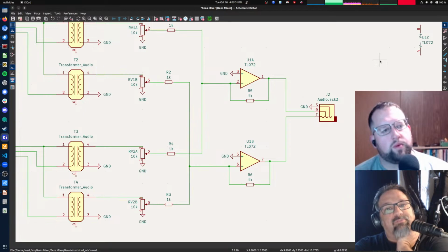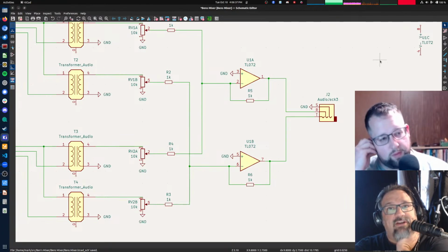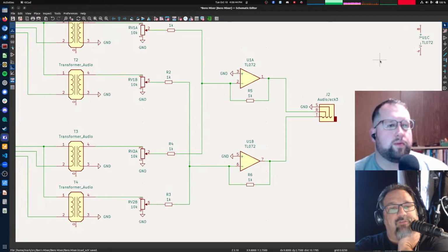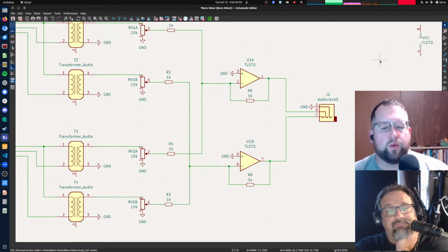Yeah, USB has other problems. USB power is incredibly noisy. Well, if you're driving it off of a computer, it's going to be incredibly noisy, and that'll come through in your headphone amplifier or in your op amps. The other thought I had would be like the 12-volt input, Anderson power poles, or the 12-volt system from your radios. That's actually what I was going to say.